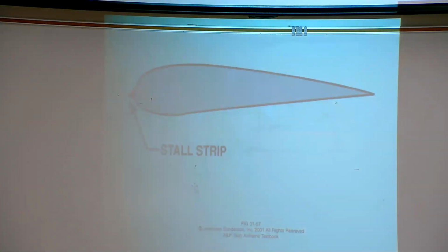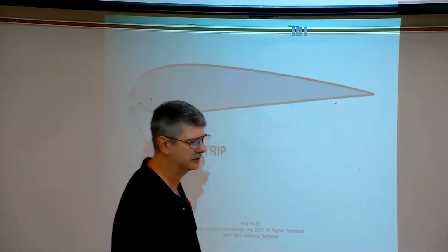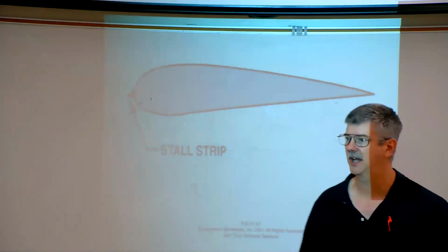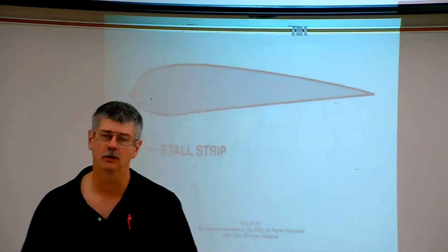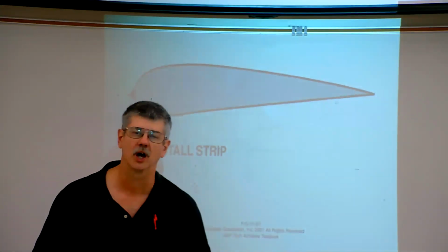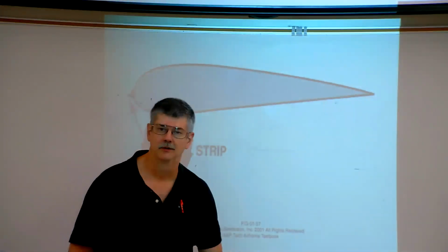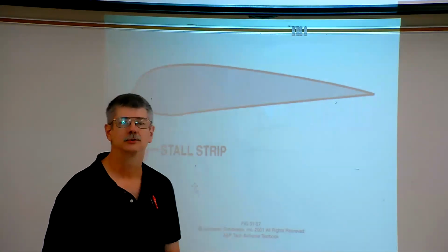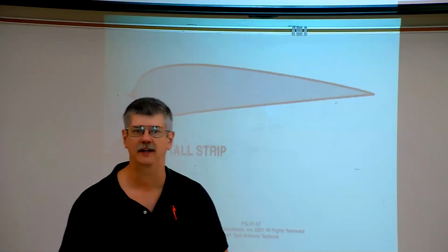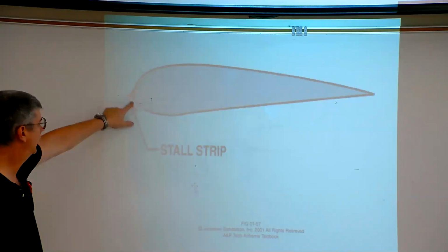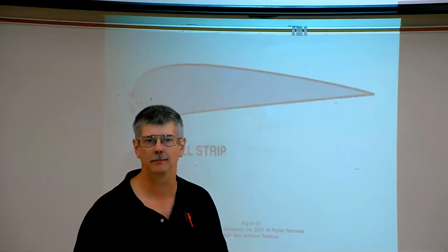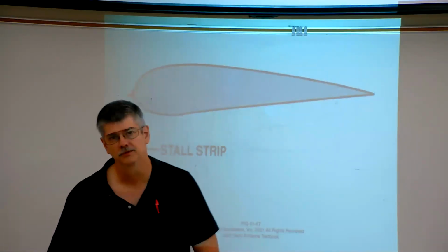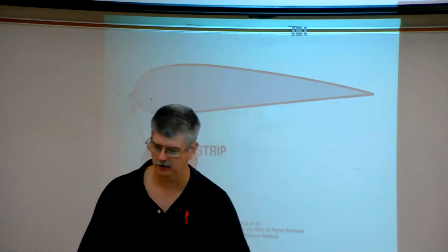Okay, all right. Sometimes engineers screw up or they find something that was unexpected. In this case, what they found was that the whole wing was stalling, or wrong portions of the wing were stalling before the area that they wanted to stall. So to promote a stall in specific areas, they can install what's called a stall strip. And that's all it does. A stall strip promotes a stall, say, before the critical angle of attack.